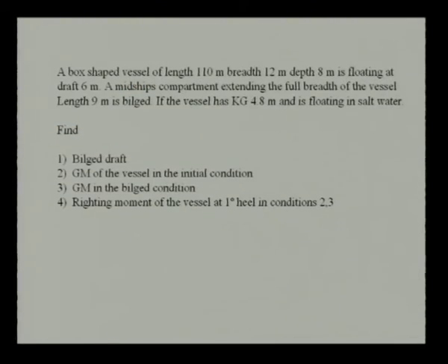Then note that even though you have flooding in this case, you are not going to get negative GM. That does not mean anything. Even though some compartment is flooded, of course in a damaged case, GM is not negative. GM is negative only in a very extreme, critical case, when it is highly unstable and maybe even capsizes. That is different. Here you will still get positive GM, the ship is still stable, but it is flooded, that is all.